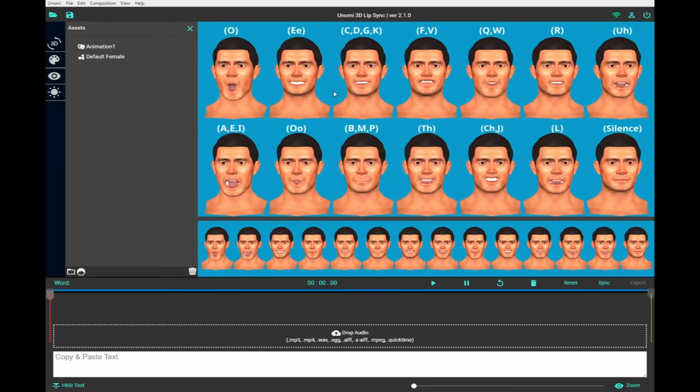We're going to use the male default model because of complications with Maya not being able to transfer blend shapes that are in your geometry. This is just because Maya's FBX export function only saves delta information of the normal invertices on the geometry. It won't export the blend shapes. Autodesk purposely did this in order for files that are exported to be very small.